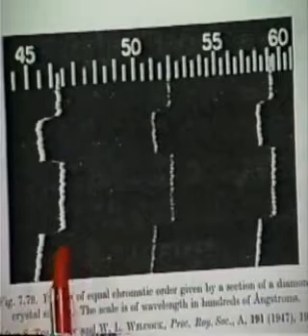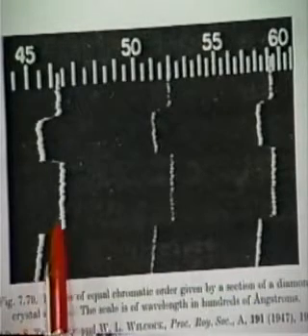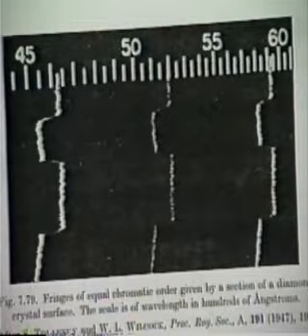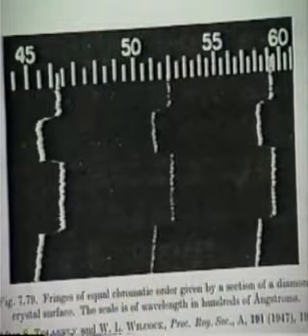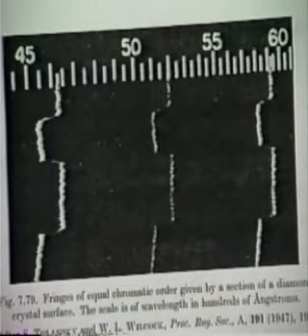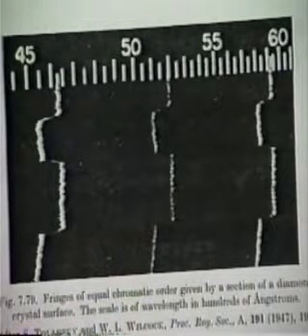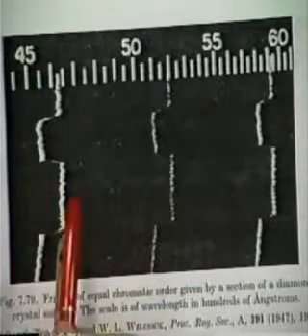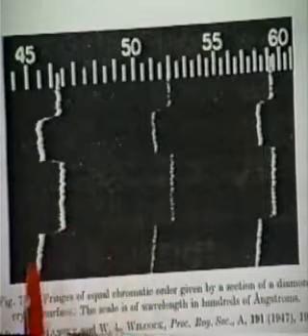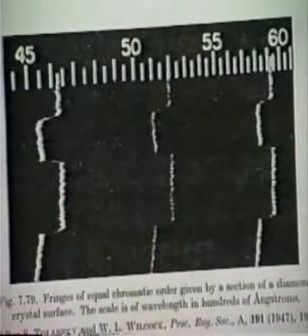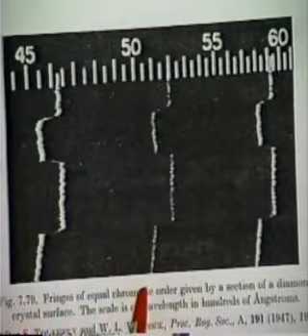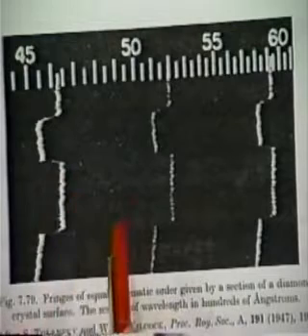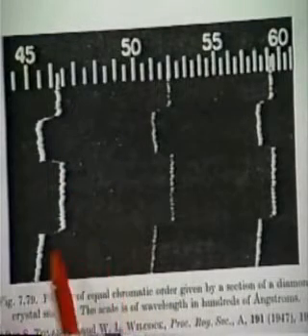So a small change in d gives you a small change in the wavelength for that fringe. And 2d is equal to m lambda. So if lambda increases, d increases. If d increases, that must be a low spot on the surface. So there's never any ambiguity about whether a point is a high point or a low point. It falls right out. And you can measure here in the angstrom range using this technique.